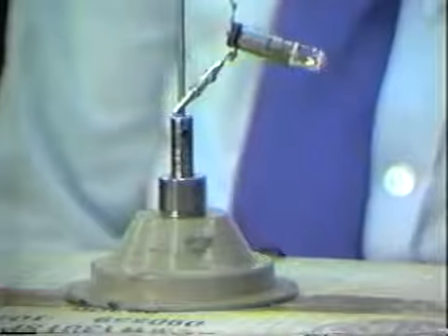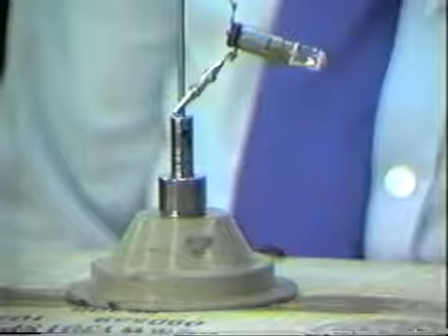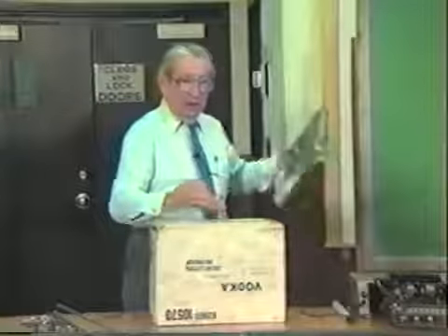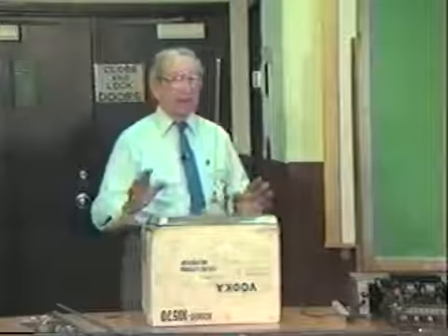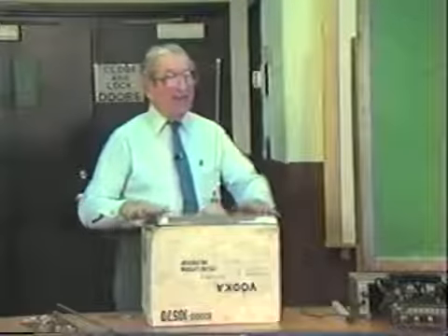I don't know whether you can see it lit or not. Probably not. Very dim. Very, very dim. Now watch what happens when I put this onto the metal pan. The antenna now is looking at resonance. This plate is filling in the other side of the quarter wave antenna as far as the transmission line is concerned, so that now the power from the transmission line is able to see its impedance and get the power into the antenna for radiation.